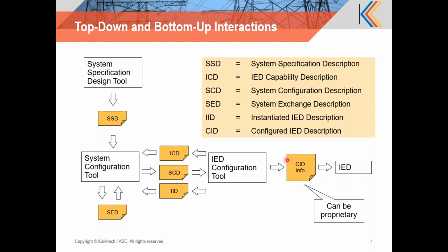the IED. Just one note here is that the CID, the configured IED description information, is a subset of the SCD, but there's no rule that states that this information, when it is programmed by the ICT to the IED, has to follow the standard. Typically, the information that is extracted from the SCD, which is the CID information, would be merged along with other information, for example, logic, which may be generated by the ICT, and that entire bundle will be programmed to the IED in one step, and that could be a proprietary usage.